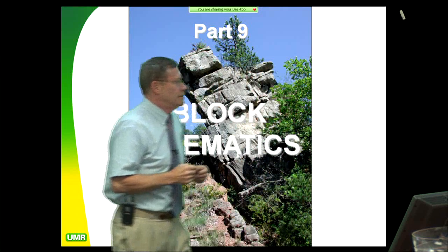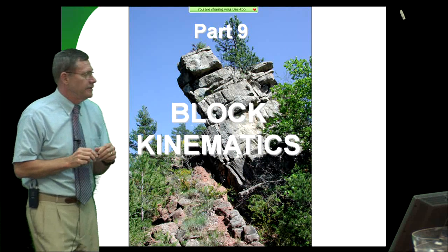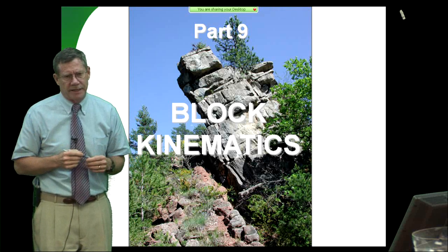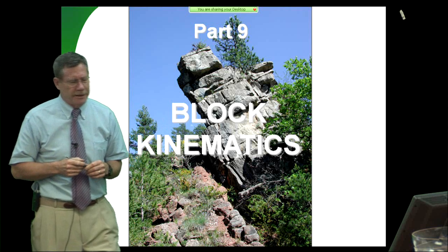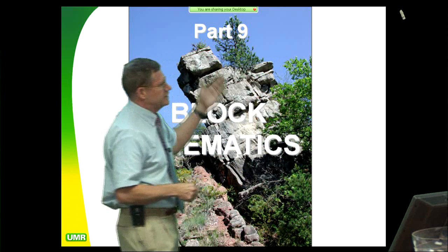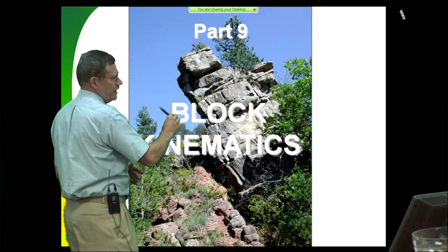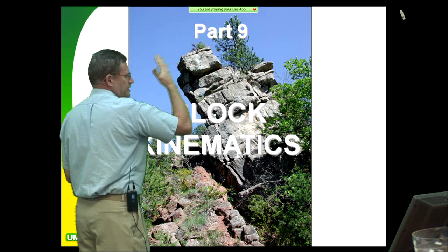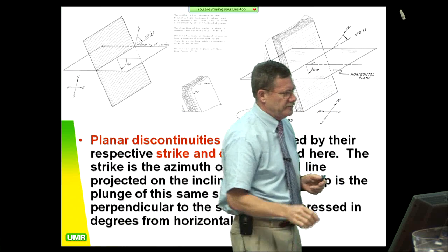Okay, block kinematics is what I want to give you a brief introduction to next. And block kinematics are something we talk about a lot in rock mechanics. If you take Professor Mayer's rock engineering course, he'd be talking about a lot of these things. What I'm looking at right here is a toppling type of failure, where you have something that's dipping 55 to 75 degrees. These kind of things can topple over just like a bunch of books toppling off a shelf.